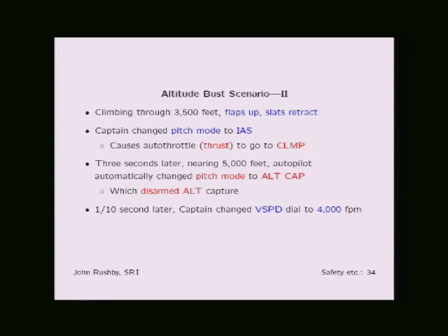I don't know why. The issue is not who is correct. Maybe the pilot is correct in this case, and the system was coded wrongly. But the problem is you want to make sure they're in sync. So either one could be wrong, and that's a different problem. This problem is you just want to make sure that the pilot's view matches what the system actually does. And of course, if the designers think this is actually a wrong thing for the autopilot to do, then you should go and change the autopilot code. But then you should make sure that the pilot's mental model still matches whatever the new code says.